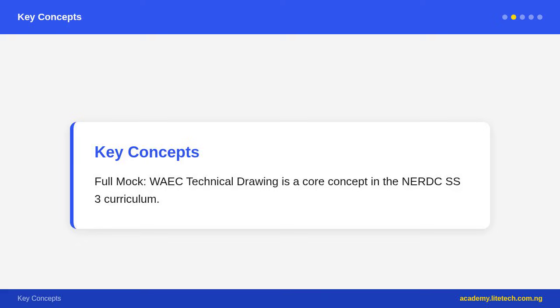The addendum circle, tip circle, is drawn as a thick continuous line. The pitch circle is drawn as a thin chain line, long short dash, centerline type. The dedendum circle, root circle, is drawn as a thin continuous line. Gear teeth are not drawn individually in assembly drawings, just the 3 circles.